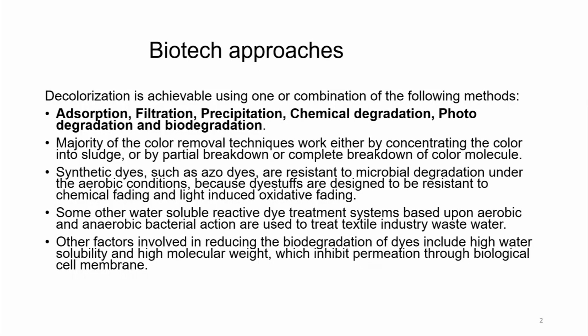Biotech approaches. Decolorization is achievable using one or a combination of the following methods. One can use adsorption, filtration, precipitation, chemical degradation, photodegradation and biodegradation. The majority of color removal techniques work either by concentrating the color into sludge or by partial or complete breakdown of the color molecule.